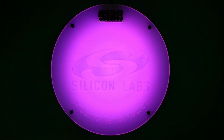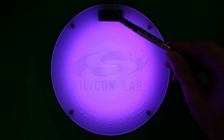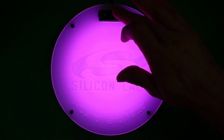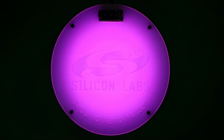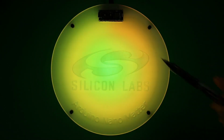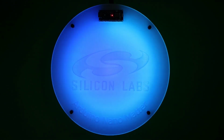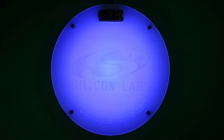Once online, it will begin displaying the short gradient mode, indicated by a triple flash of the onboard LED. The default colours in this mode will cycle from blue through to magenta and back again. Pressing the button will switch to the long gradient mode, indicated by quadruple flashes of the onboard LED. The long path will cycle from blue through cyan, green, yellow and red to magenta and then back again.